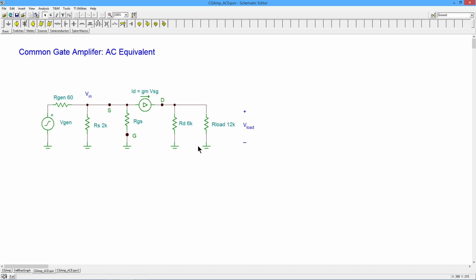All right, so if we think of that in terms of a formula, then you're talking about gmVGS, right? There's the VGS again. gmVGS times the resistance. On the input, V in is VGS. So what ends up happening is you have a VGS over a VGS, they cancel, and you end up with a gain that's just gm times the AC load resistance. No inversion, right? Positive input gives me positive output.